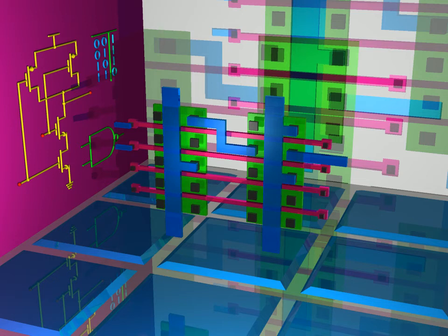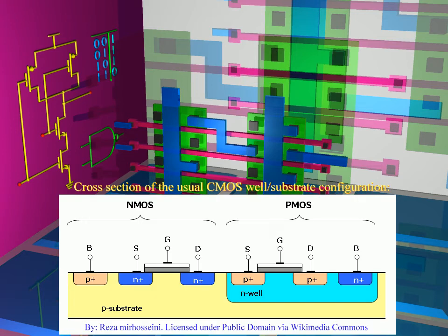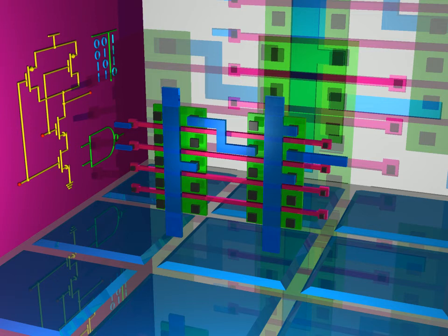Technically, the NMOS transistors have an understood or assumed P-type well diffusion, which would mean this design has an N substrate. This seems to be a little unusual, as most seem to have an N-type well diffusion on the PMOS transistors instead, and a P substrate. I didn't model the well diffusion distinction. Perhaps I should have. Here's what it might look like if I did.